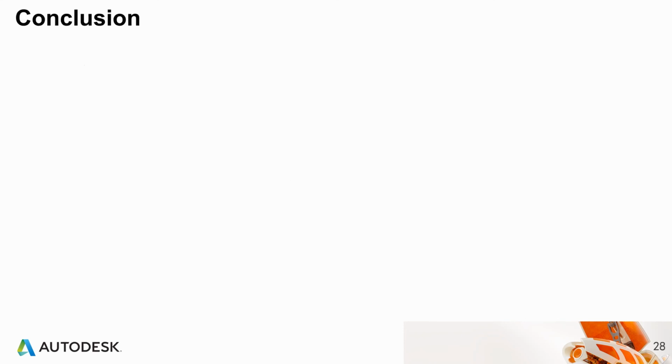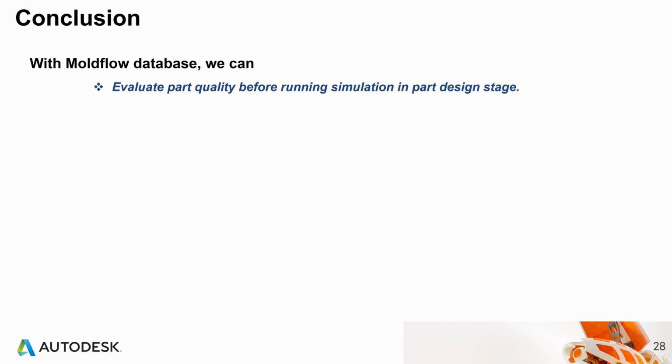Finally, to give a conclusion. With the Moldflow database, we can evaluate part quality before running simulation in the part design stage. If we find the part quality is bad in the part stage, we can require the part design to optimize the part structure, and we don't need to do Moldflow simulation at the moment. And then we can define gate location quickly and reduce simulation times.